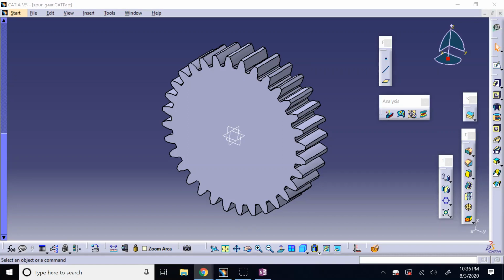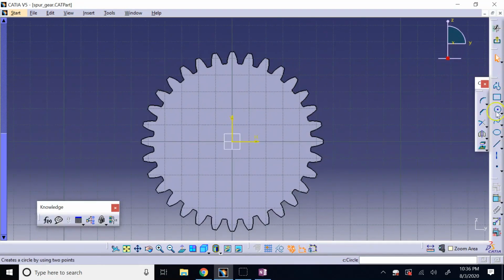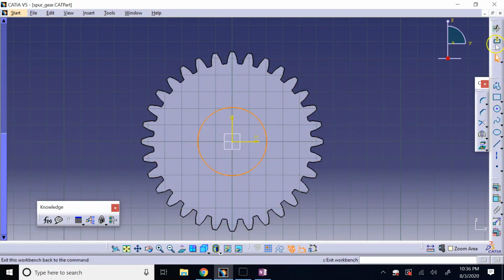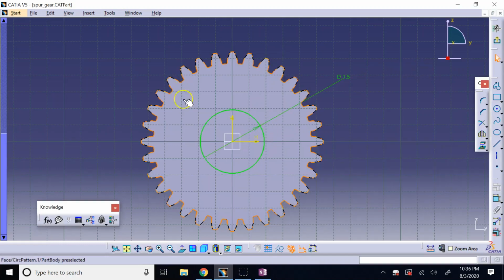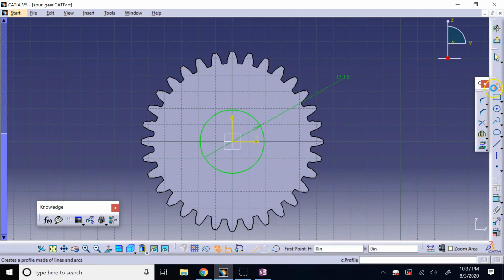I went all the way to the beginning of page 16. I don't need to go to helical right now. Just one last thing I want to show you is a hub and a keyway that is typical in gears. So if you know that, let's say the size of the shaft that you have in a gear is, let's say, 1.5 inches. Okay, so then you create the hole for that. Of course, you need to know the tolerance as well. And then you create a keyway, right? And I'll show you how to do a keyway.